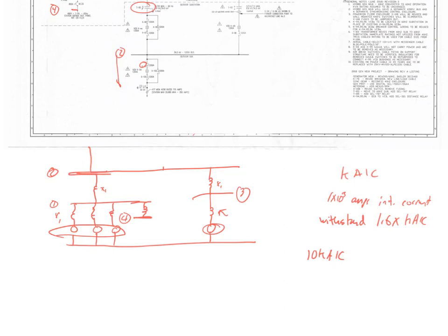And if you look at a fuse, you can actually see some of the glass that has been converted. It's pretty crazy. So if you Google cutting open a melted current limiting fuse, you might be able to find some where you can see the glass. Pretty interesting stuff. So it's 1 times 10 to the third. That's K, right? It's just a K, or kilo? Yeah. Of the fault current? Nope. KAIC means this breaker, or whatever it is, can interrupt 10,000 amps of current without being damaged. That's what the 10 KAIC stands for.